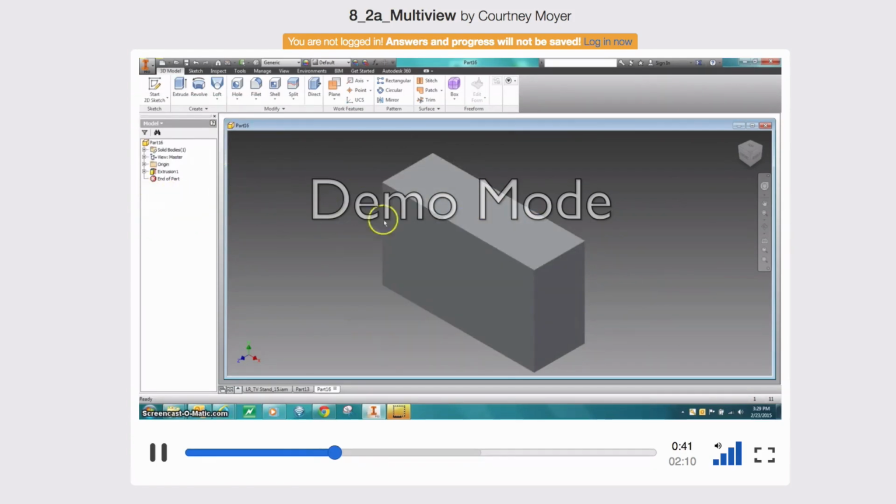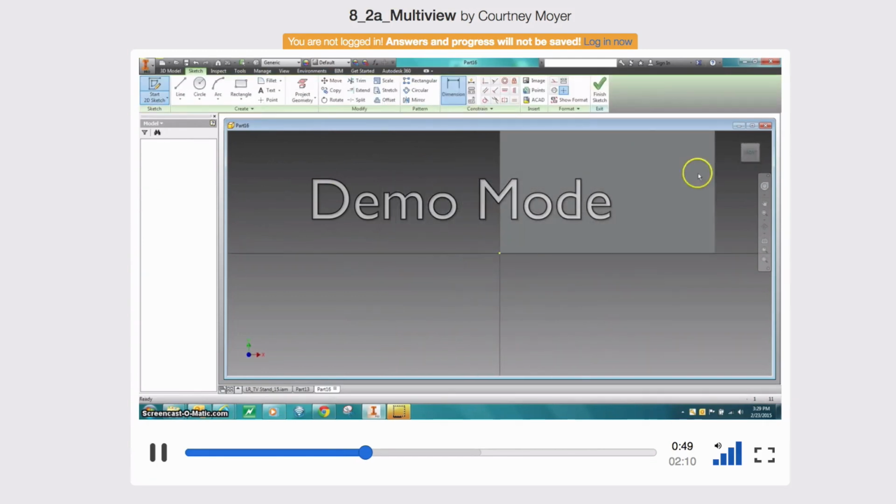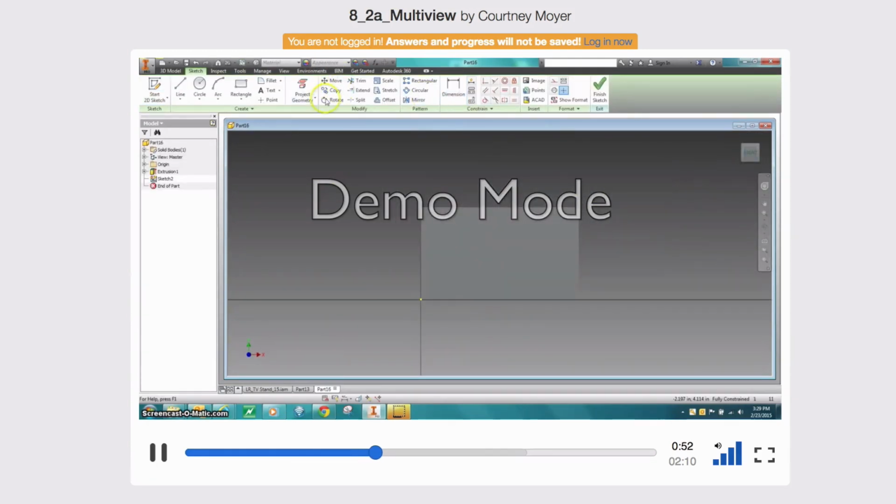All right, now this is the second one in the row that we've done by making the actual three-dimensional rectangle first. I'm then going to create a sketch on top. We're going to project geometry again, and I'm just going to create a rectangle somewhere in the middle. Now, according to your drawings, it is 0.5 inches from the top, 0.5 inches from the bottom, 0.75 inches from the end, and 0.75 inches from the end. Okay.